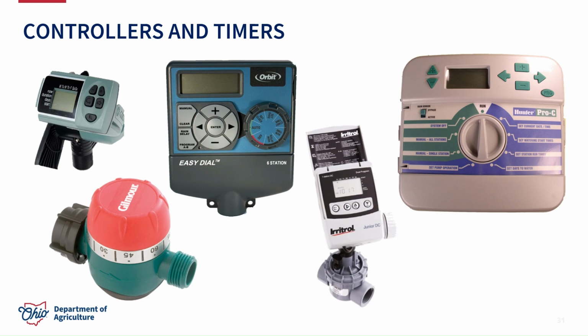The first we're going to talk about is controllers and timers. We need to have a way to control when our microirrigation system is on, when it is off, and what field it is running to. These can vary in complexity from something as simple as a manual timer that we may twist on for a set irrigation time, to a multi-zone controller with automatic valves that open and close and control the water distribution to multiple fields throughout a full, let's say, 20-hour irrigation period throughout the day.